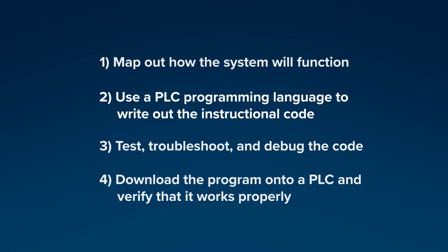A PLC will use the program's logic to determine if it should change the state of an output, depending on the state of an input, the status of a timer, a combination of several input states, etc. For example, a PLC programmer may include directions to turn an alarm, the output, to on when a tank sensor, the input, exceeds a certain temperature. Now, let's look more closely at step 2.